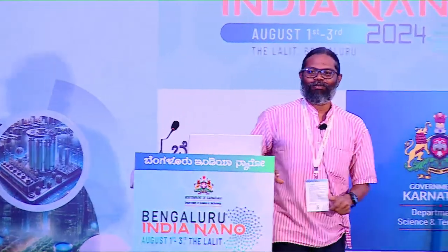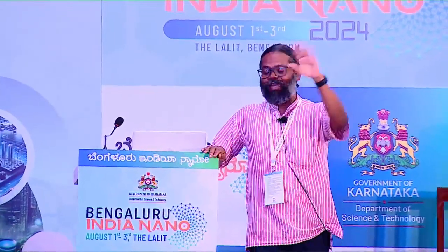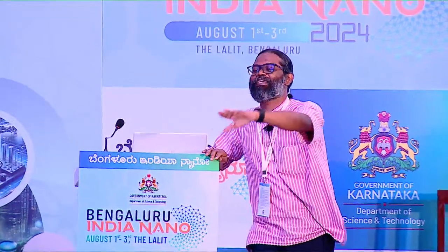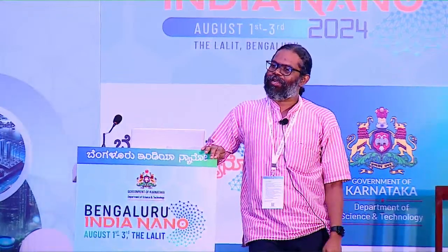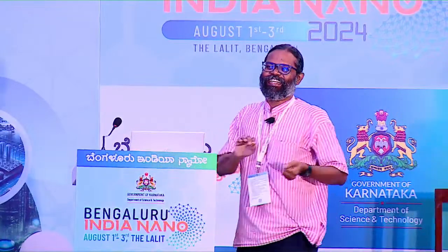Sir, excuse me. What about the mask layers? How many mask layers have you provided? It depends on the technology. Probably Saurabh would know, but for every step, every layer, a mask is required, except the silicide layer where we don't need any mask. But it depends on the complexity. So it increases, technology to technology. Good. Thank you very much.